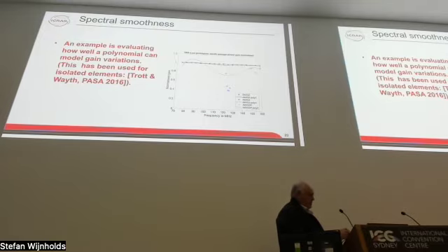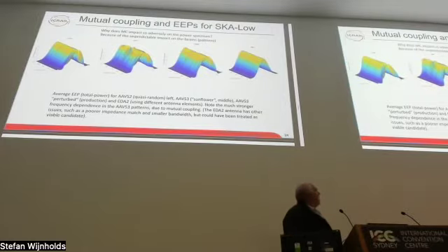What I've got over here is the same thing, but now we're looking at the average elements. If you do a plot where you try to put a fourth order polynomial through the average pattern for the AAVS3, which had a particular problem, you see you really are battling, and it's partly because the normalized gain has dropped very badly.